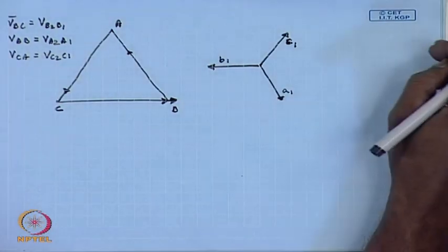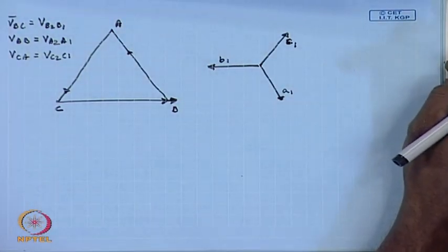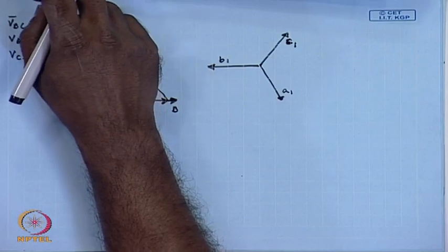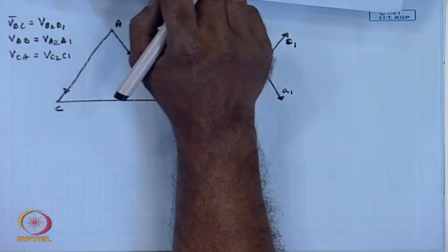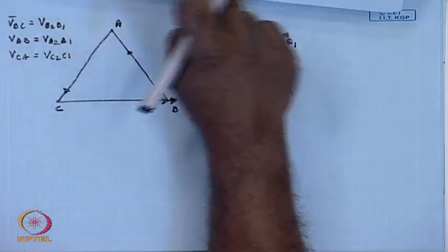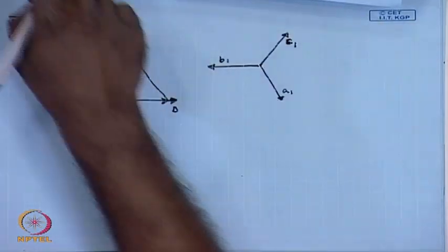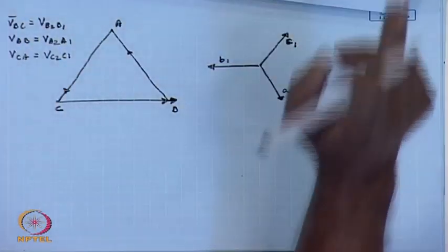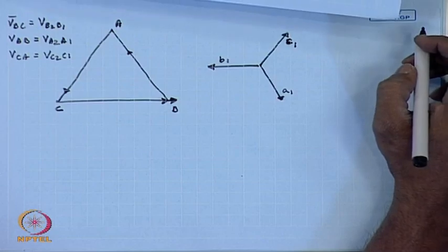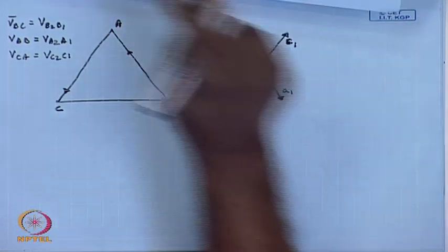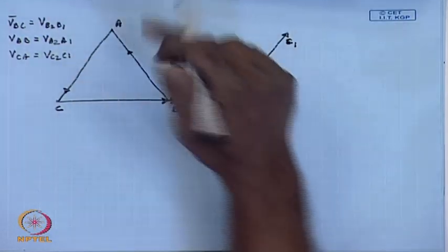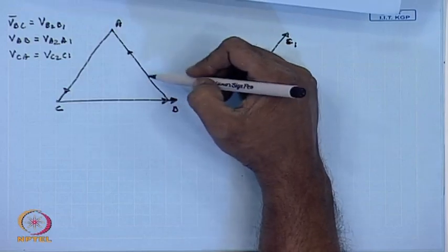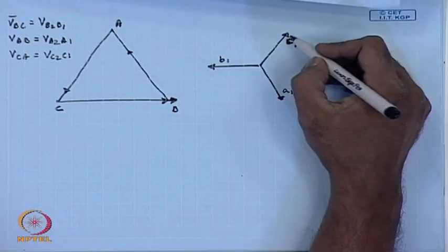Now, the phase A is obtained by adding the phasor V A4 A3 with that of A3 connected to C1. So, phase A is obtained by adding A4 A3, which is parallel to V A2 A1, with this phasor.